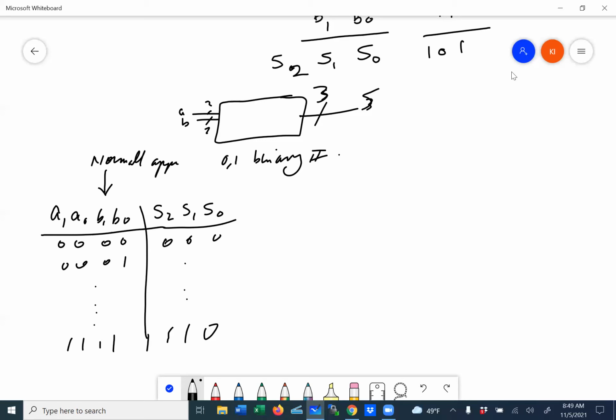The problem with that is it gets really complicated. The 2-bit is almost manageable, but it's difficult. For a 3-bit, 4-bit, 5-bit, or 16-bit adder, it becomes really, really difficult to do. So we're using this one for our lab to give you an idea that you can actually do a modularized design. Even though there are more steps, the end result is simpler.